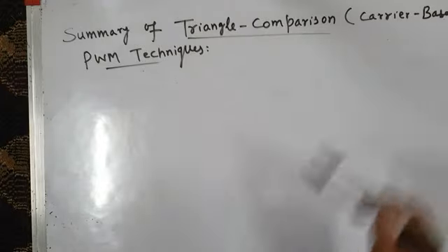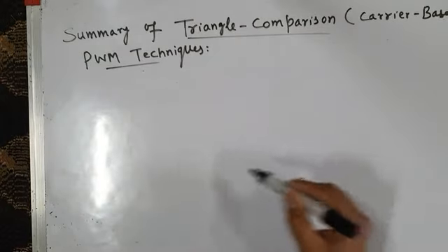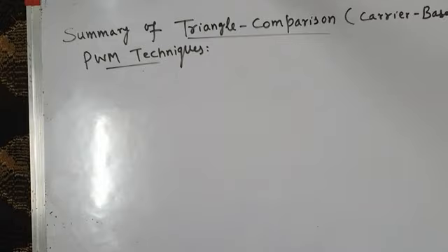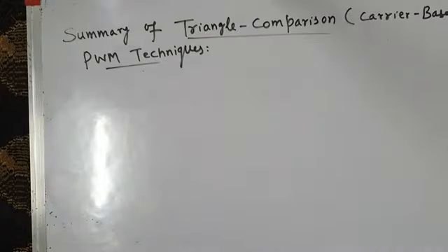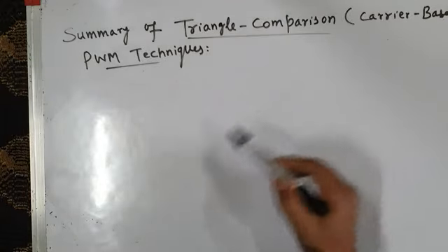They are also called carrier based PWM techniques because the reference waves or the modulating waves have to be compared with high frequency triangular carrier. This high frequency wave, which determines the switching frequency of your inverter, is also called carrier wave. So this carrier comparison is always there.